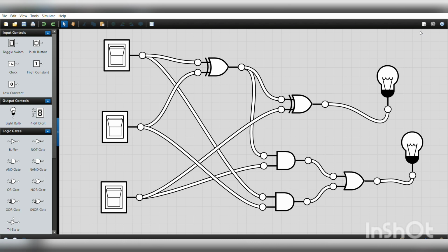I have designed all these circuits based on the circuit diagram, and let us see how the input and output operation works. So moving on to the full adder circuit. A full adder circuit generally consists of an XOR gate, AND gate and OR gate. So the sum equation is given by A exclusive-OR B exclusive-OR C and our carry equation is given by (A plus B) into C plus AB. So this is our sum output and this is our carry output.